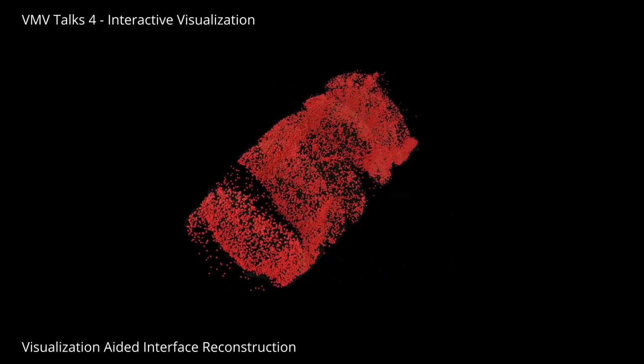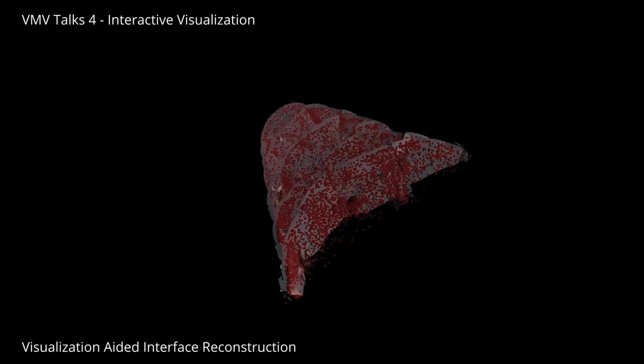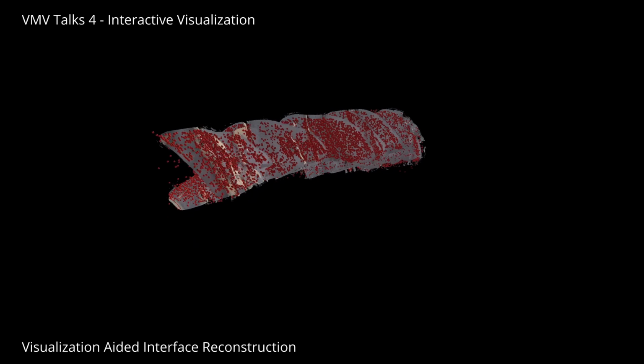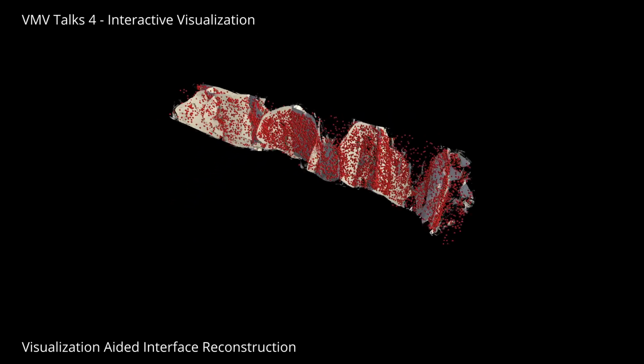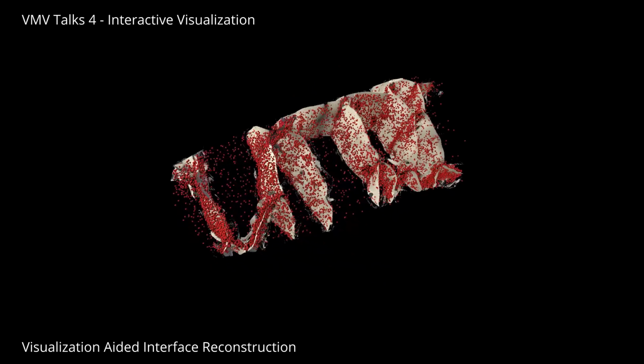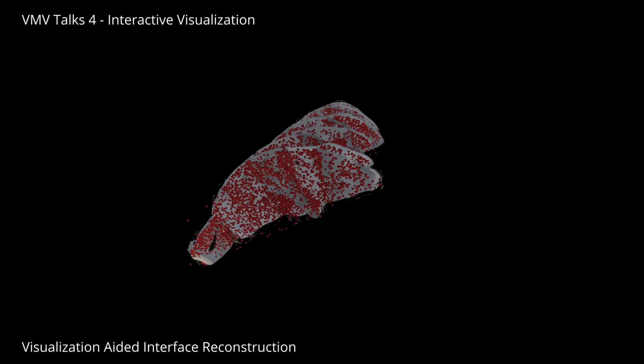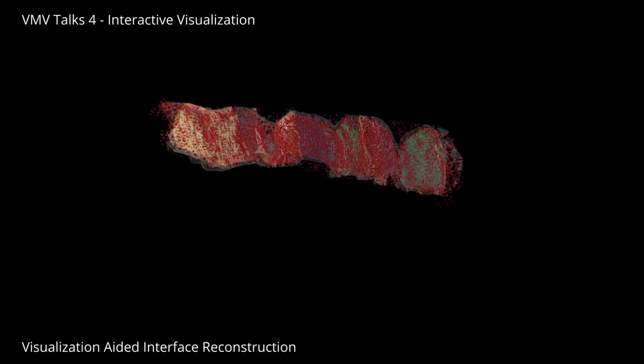In the first step, the user can tweak filter parameters for the point cloud and is presented with an interactive ray-marching-based visualization of the resulting surfaces. The boundaries are given by ridges in the point density. Then we propose a semi-automatic reconstruction method which generates the parametric representations of the visualized surfaces.